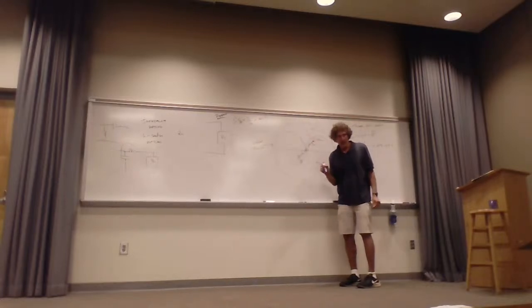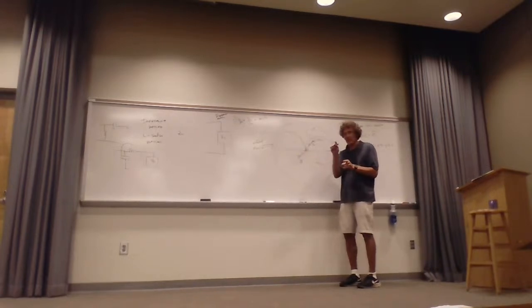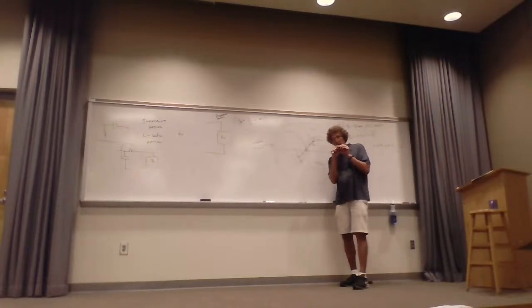Typically, we like capacitors, just saying, if it's in parallel. We like capacitors in parallel for one reason, because they don't pass DC. And oftentimes, with microwave circuitry, we have a DC offset. You know, with your BJT transistors, you have to get a DC current going through those that sets the bias, right?